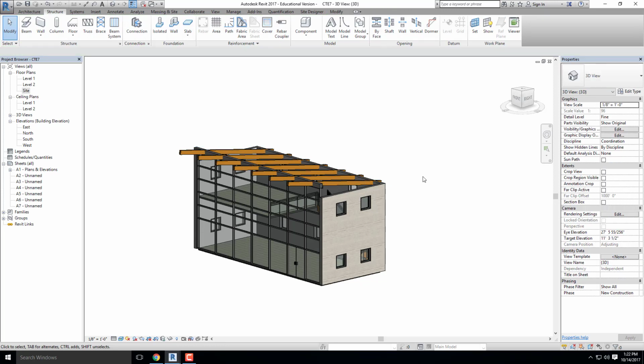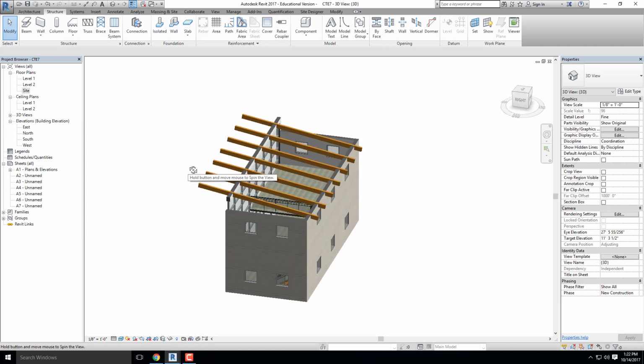No, you don't have to. You can draw anything you want in any view you want. All the views are there for your use. So if you like, I can draw in my floor plans, my elevations, or my 3D views. It's just whatever your preference is. I've gotten used to drawing things in whatever view I want, because as soon as you start to understand reference planes enough, it doesn't matter what view you're in, as long as you understand where your reference plane is, where you're drawing, okay?